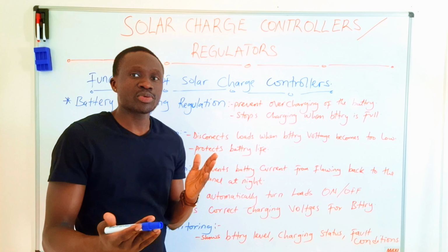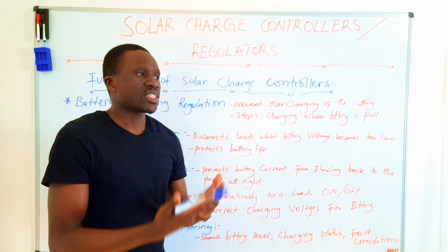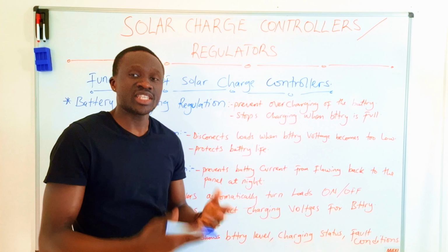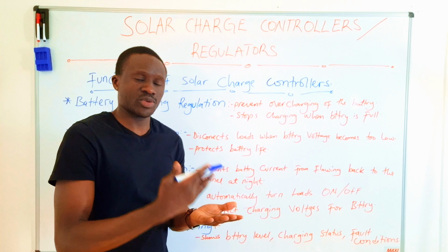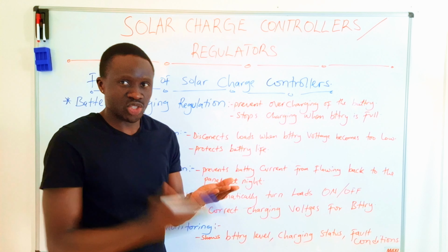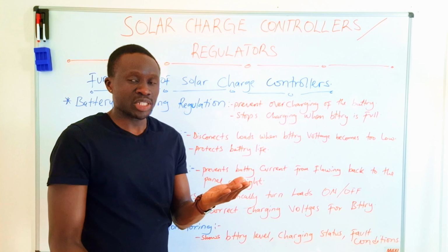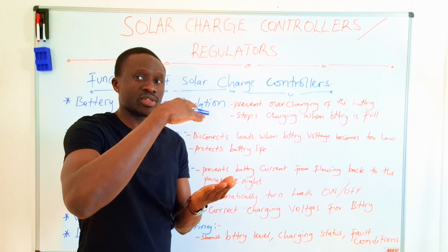But once you install it for a customer without a charge controller, you will see the system die in a short period of time. But once you install it in a proper way, with a solar panel, then a regulator, then a battery, you can supply power to the loads.